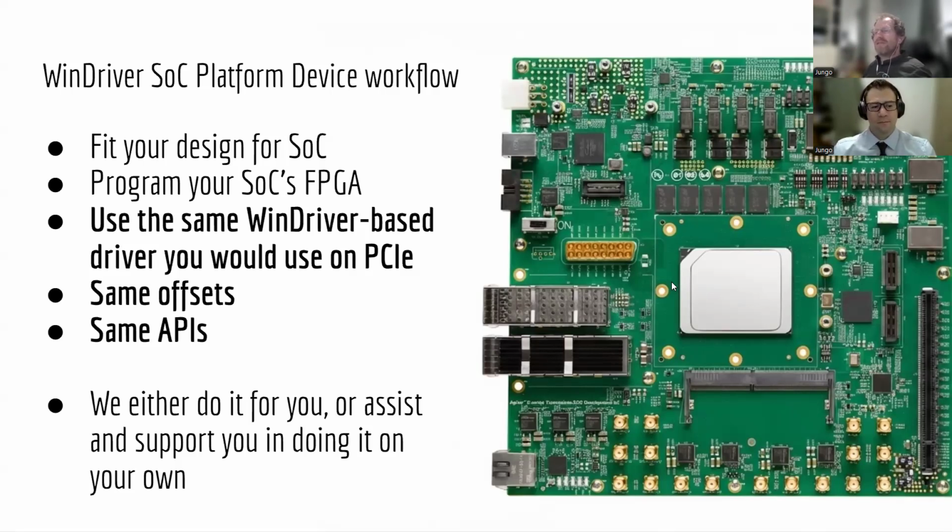Once you fit your design for SoC, you need to program your SoC's FPGA. That's also something that you need the IDEs from the vendors to do. Then you need to make your platform device identifiable by your operating system. That usually also comes with the IDEs. But we're also going to make a feature that allows you to add your platform devices using WinDriver so that the operating system will be able to identify them. And if the operating system identifies them, then WinDriver will be able to identify them.